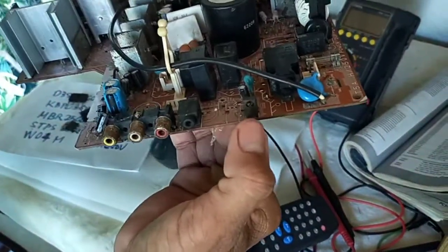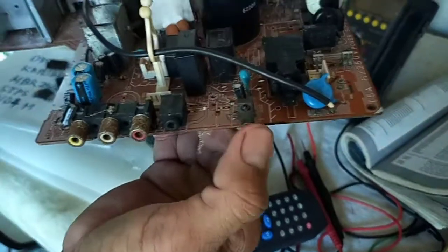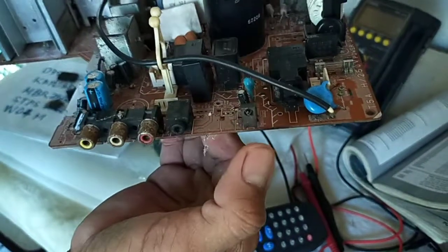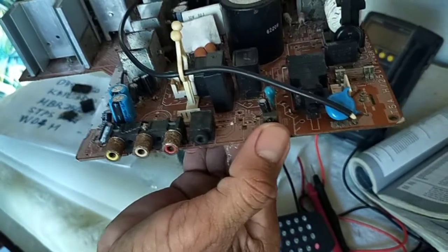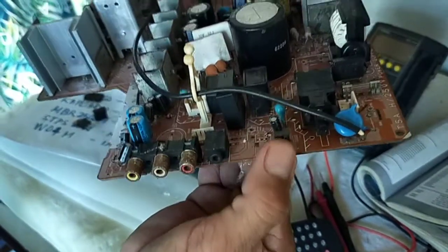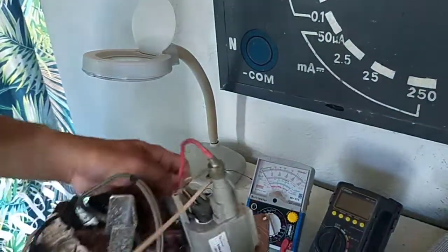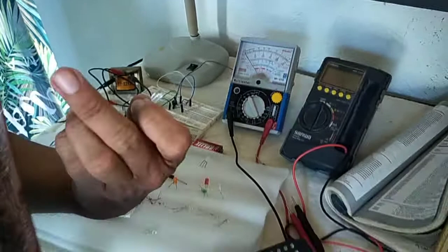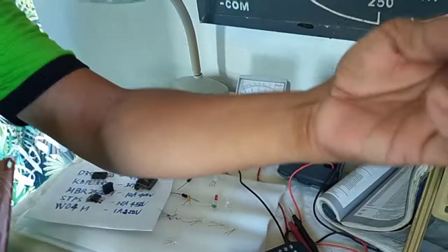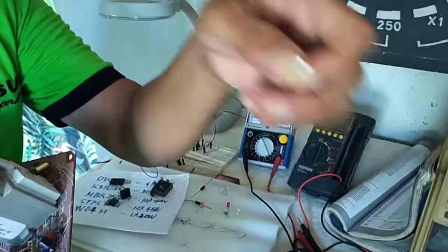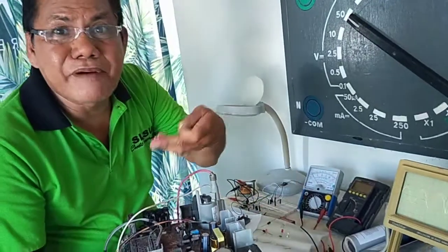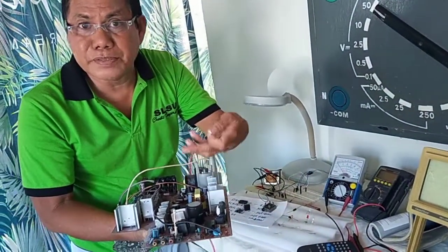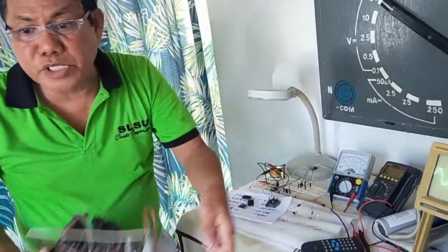For the TV receiver, we have here the infrared sensor, or we call it the infrared receiver. It is actually a photodiode but combined with a PNP transistor as an amplifier. It has 3 terminals, but the actual photodiode is 2 only. Because the photodiode receives the signal being transmitted by the remote control via the infrared LED. After it is received by the photodiode, it is then amplified by a transistor. That is for the infrared sensor.